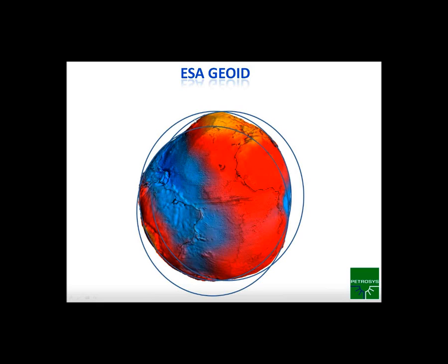And then what you end up having is a geographic CRS that's designed for different areas. So in the case of this line, if you wanted to map some things over here in Africa, it might be necessary to use a spheroid that's oriented in such a way that the surface overlaps over on this side. And there's lots and lots and lots of different spheroids in the geographic CRSs.